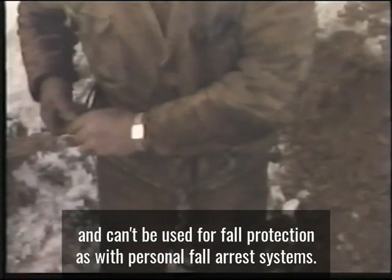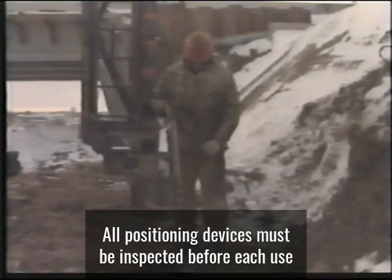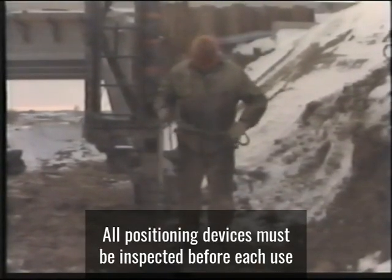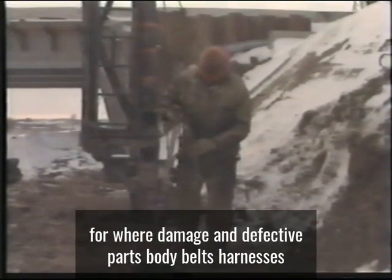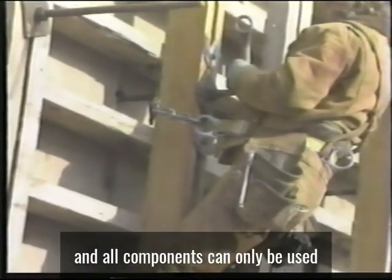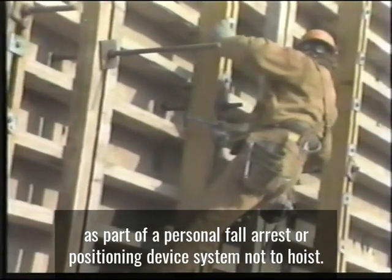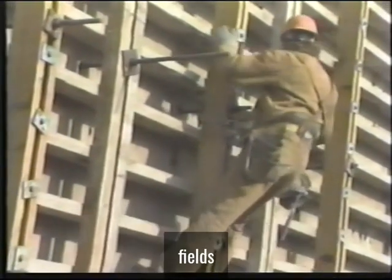Note that these belts can only be used to hold you in place while you are working and can't be used for fall protection. As with personal fall arrest systems, all positioning devices must be inspected before each use for wear, damage, and defective parts. Body belts, harnesses, and all components can only be used as part of a personal fall arrest or positioning device system, not to hoist materials.